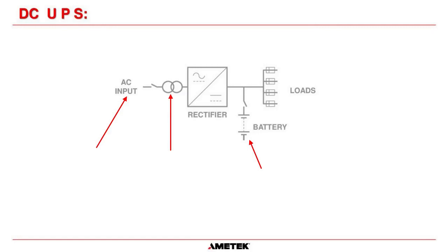And then the batteries are in parallel with the DC bus, so they are always there being charged, and if anything happens to the rectifier, the batteries will continue to supply power out to your load circuits out here. Okay, so that is the most basic rectifier charger system that you can get.